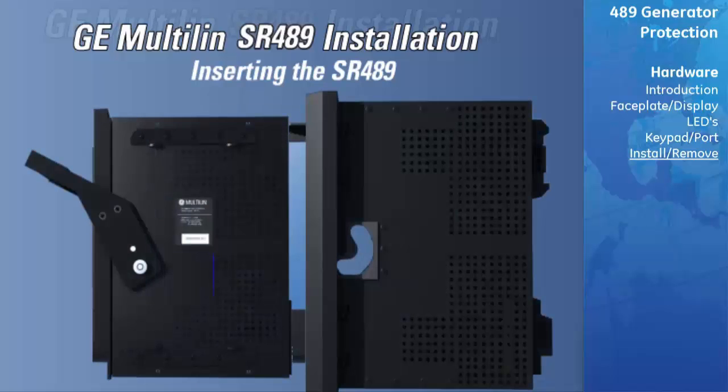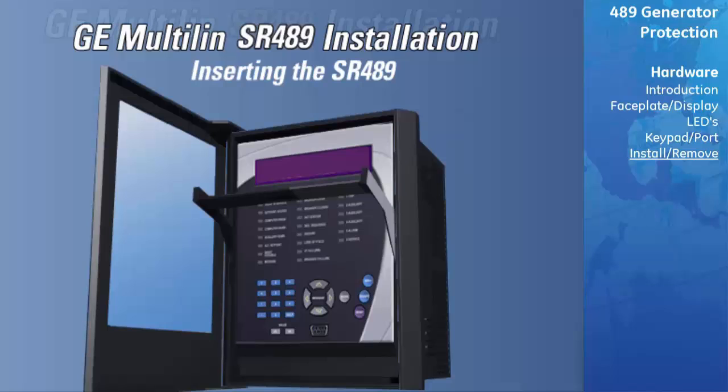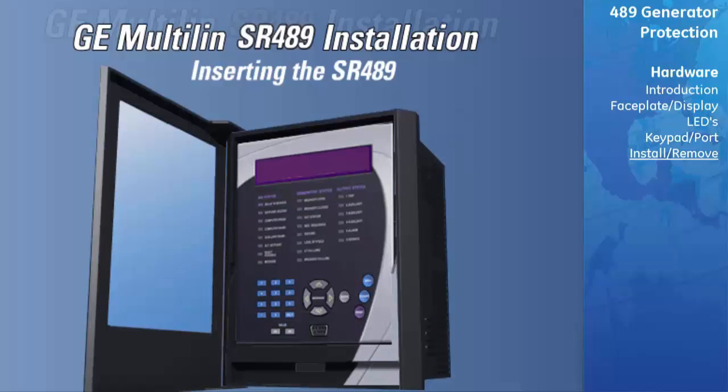Slide the unit into the case until the guide pins on the unit have engaged the guide slots on either side of the case. Grasp the locking handle in the center and press down firmly, rotating the handle from the raised position towards the bottom of the unit. When the unit is fully inserted, the latch will be heard to click, locking the handle in the final position.